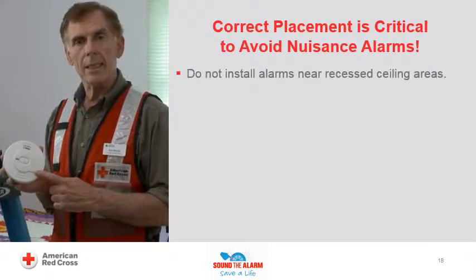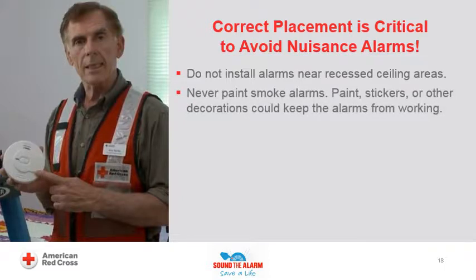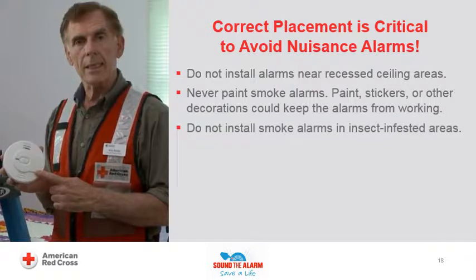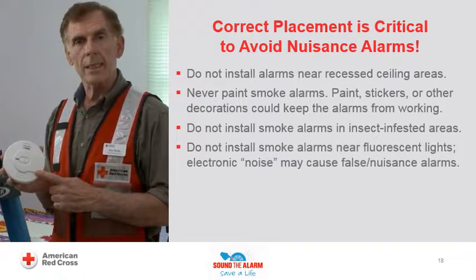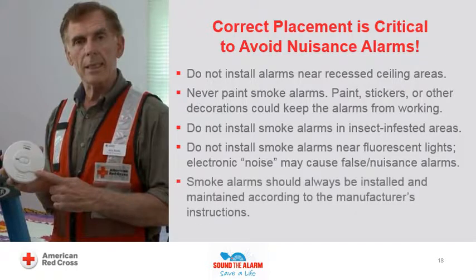Do not install alarms near recessed ceiling areas. Never paint smoke alarms. Paint, stickers, or other decorations could keep the alarms from working. Do not install smoke alarms in insect-infested areas. Do not install smoke alarms near fluorescent lights. Electronic noise may cause false nuisance alarms. Smoke alarms should always be installed and maintained according to the manufacturer's instructions.